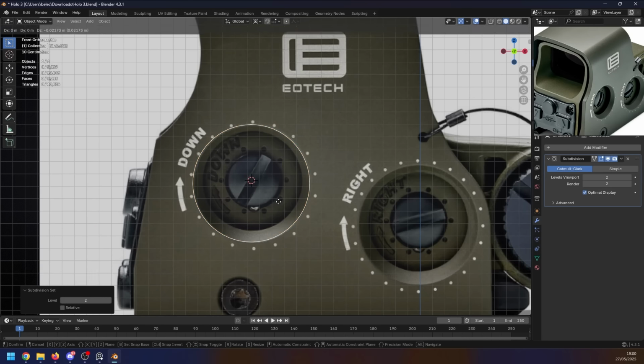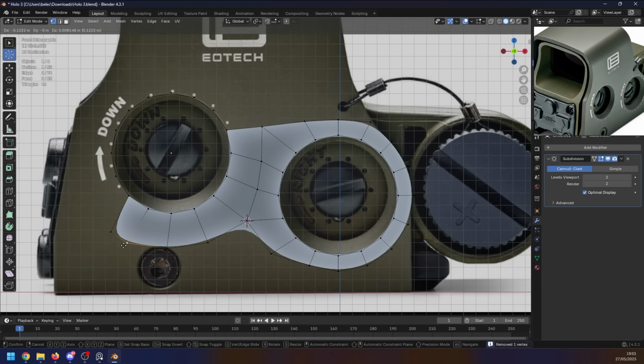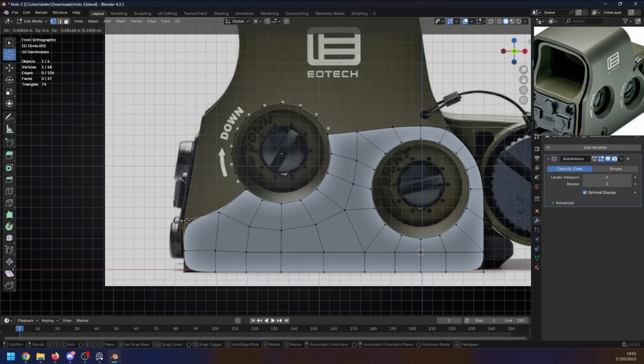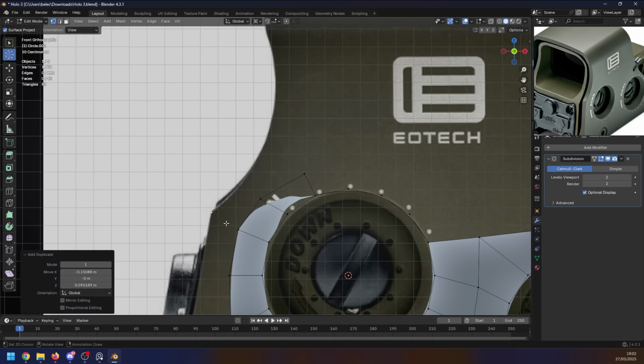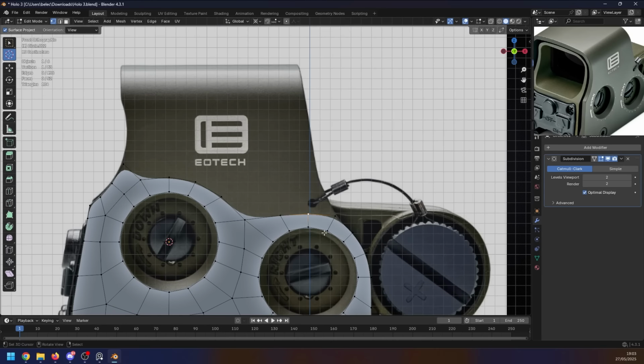Now to create the outer layer, I started with 2 circles. Each of the circles has 16 vertices, and then I just extruded everything out of those 2 circles, and I manually constructed the entire shape from side view, as you can see right here on this time lapse. There is not really too much to say here. As you can see, I'm just using some very basic hand modeling techniques.